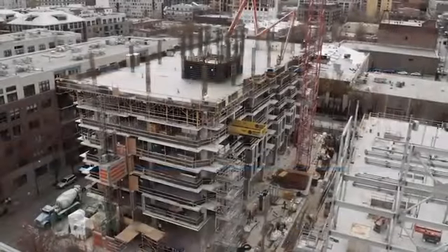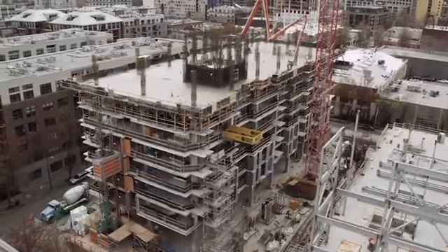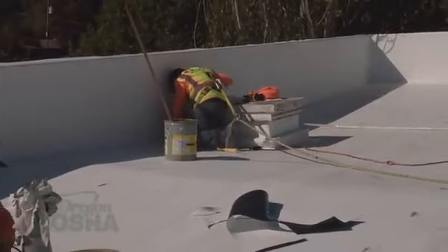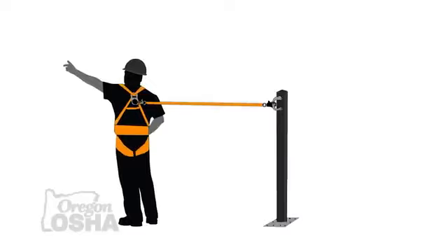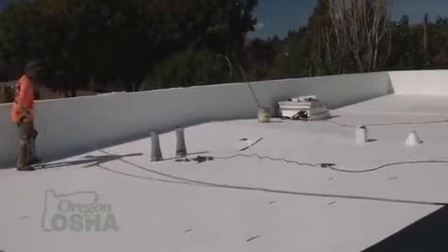We see fall arrest and fall restraint talked about quite a bit, and it seems like there is some misunderstanding between the two. When I'm working in fall restraint, what I like to describe that as is I'm like a dog on a leash. I have a fixed length connector going back to an anchor point that is set in such a way that when I have that extended out to its maximum length of travel, I can't get to that hazard. If I'm working next to an edge, I can't get my feet, I can't get my butt over that edge. There's no way I can fall. My system is actually set up to catch me and protect me before I have a chance to fall.